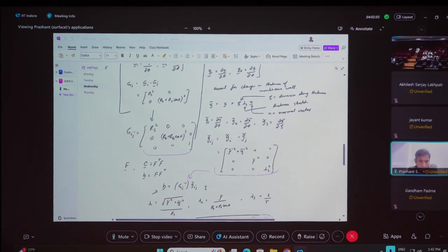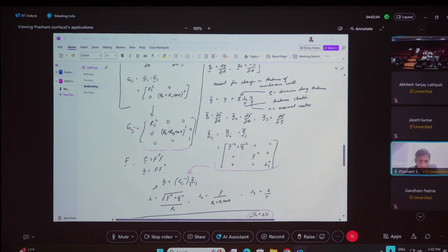From that you see it's a diagonal tensor, and then you can get lambda 1, lambda 2, and lambda 3. So we were able to find out what the stretches are by looking at the geometry of deformation. And the stretches, of course, depend on these functions rho and eta, and also on the initial geometry, which is RB, RS, and so on.